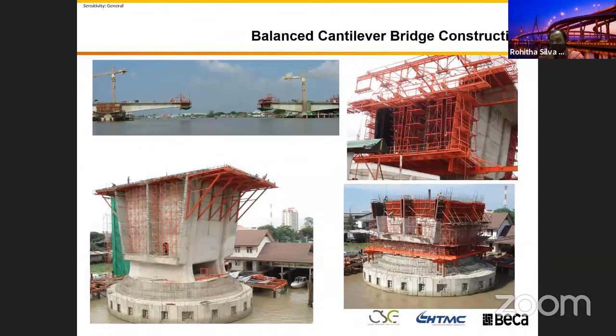do those assessments. The reason why I said these bridges have a significant capacity is because, you know, when you are designing a cantilever beam, anybody can design a cantilever beam. That's what we learn in our second year. When you are designing a cantilever beam, your tension is on the top. So in these bridges, you just keep adding the pre-stress, because you can't design with reinforced concrete. Pre-stress on the top.